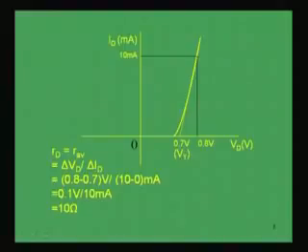So, this is the average resistance, or the order of the resistance of a diode is around this, that is, it will be in the order of ohms. So, here we have got 10 ohm. So, now the information of this average resistance and this cut-in voltage or threshold voltage, which is 0.7 volt around for silicon and 0.3 volt for germanium, these two things are enough information to model the diode, that is the cut-in voltage and this average resistance.